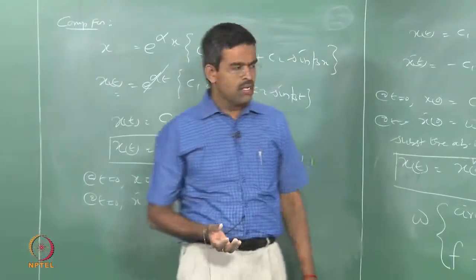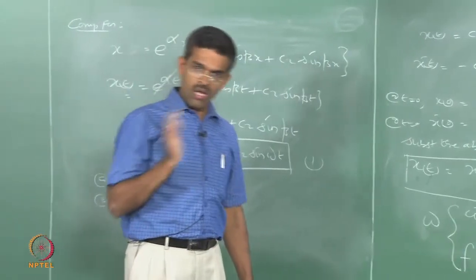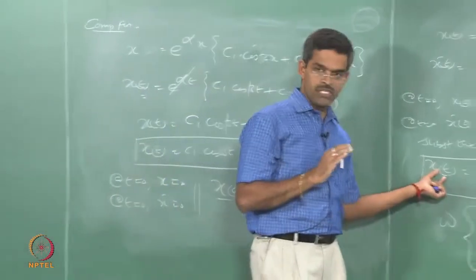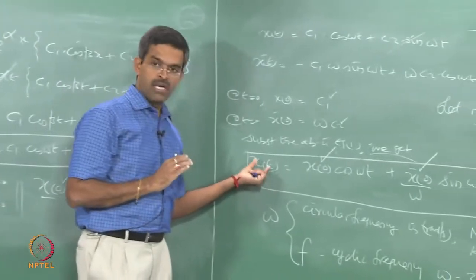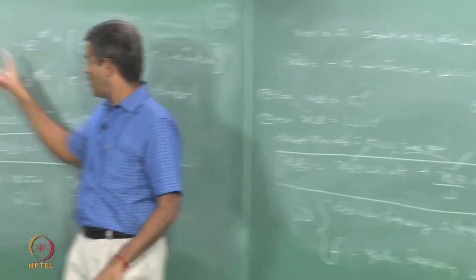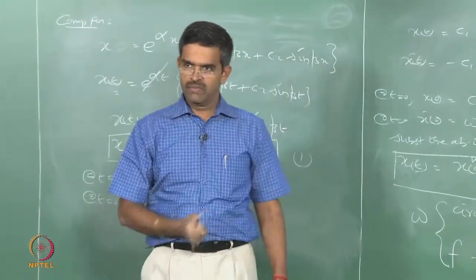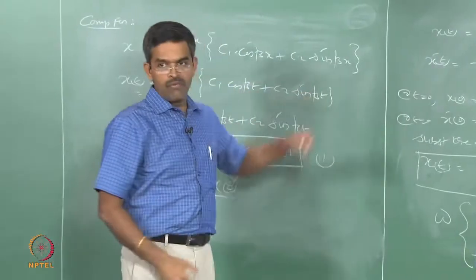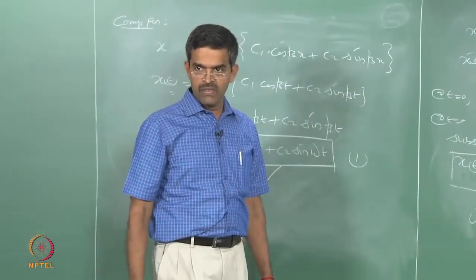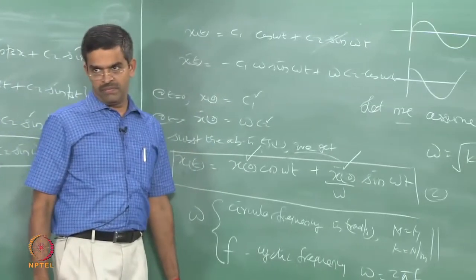Okay. So, very easily for a given mathematical model, I can write the equation of motion, solve it, and get the solution, which is the dynamic response analysis of the single degree of freedom system under the given condition of m present, k present, c not present and f of t not present. Similarly, we will look into the other remaining 4 conditions one by one in the next classes, and we will see qualitatively, we will plot them and see how they look.